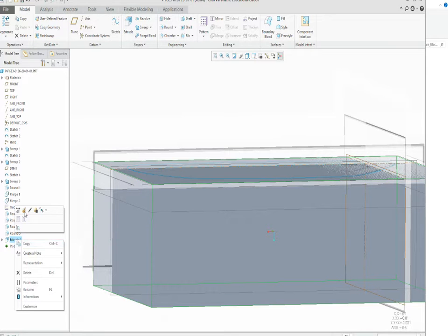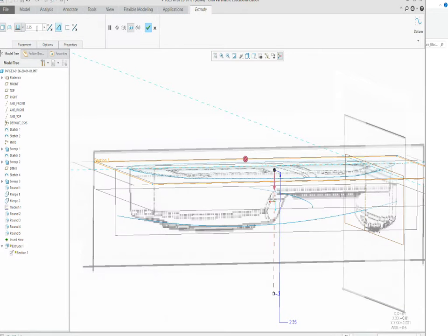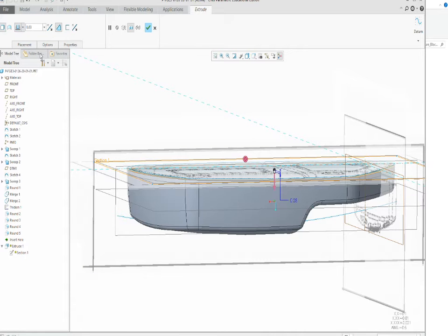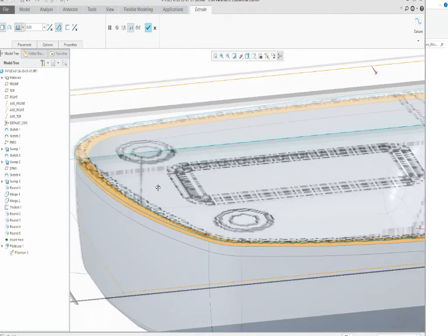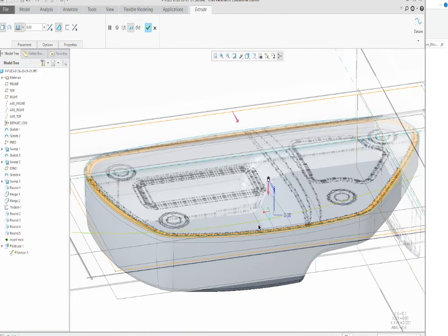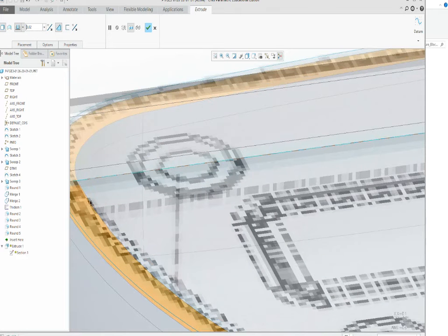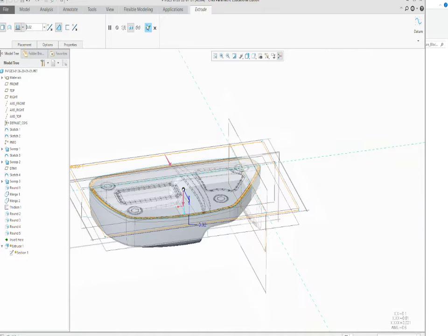If you hit extrude or hit return, make sure you're removing material, and then you only want to remove, let's say, about 30 thousandths on the part. When you see that 30 thousandths coming off, you're going to see it orange all the way around the rim. If you only see half the rim, cut a little bit more. So let's go with 20 thousandths, and that looks good all the way around the rim.